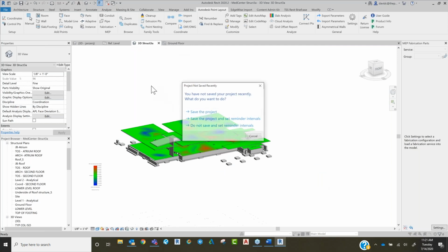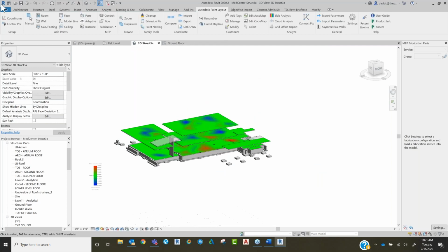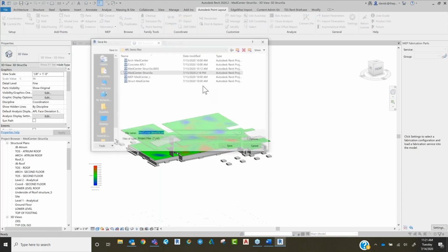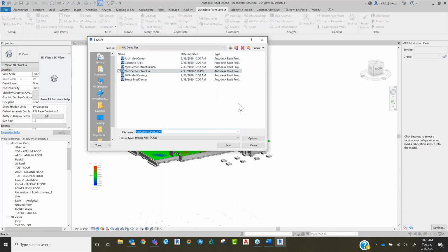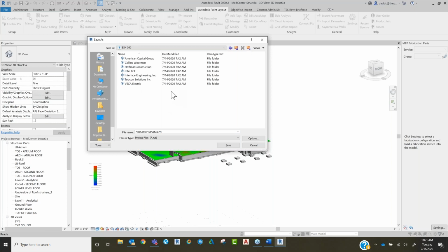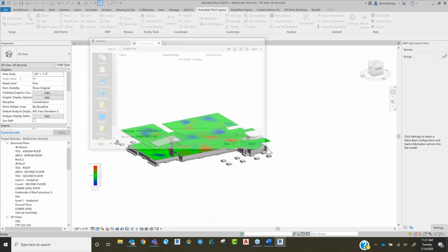The other way to do this is you can use either the cloud file, you can also use project, and then instead of going through that window we just had, you can utilize your desktop connector again. Here's BIM360. The desktop connector installs like a map drive right to BIM360, and it's going to give you all of the accounts that you're working with and then all of your different projects. So we just path ourselves right back into that next gen layout with project files, and we can save our model there.